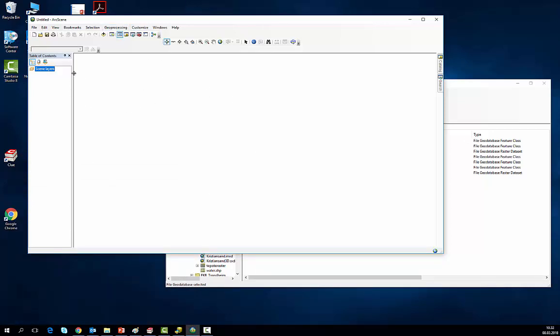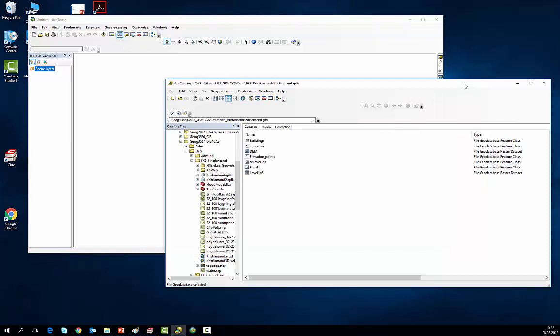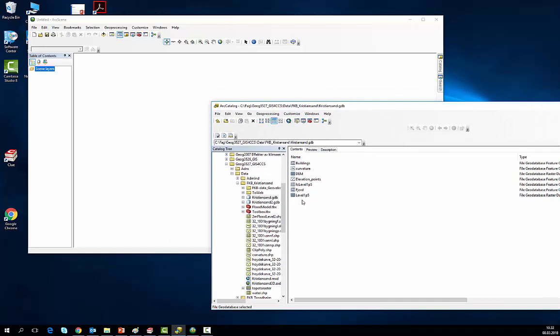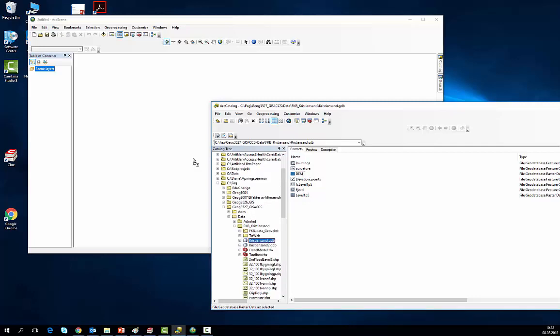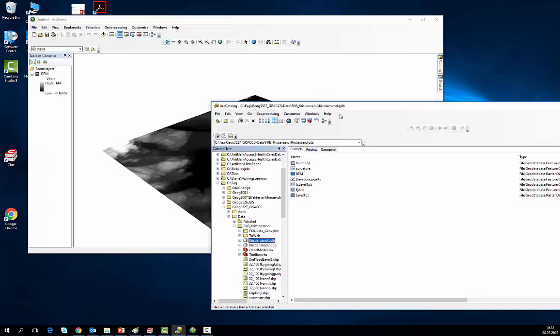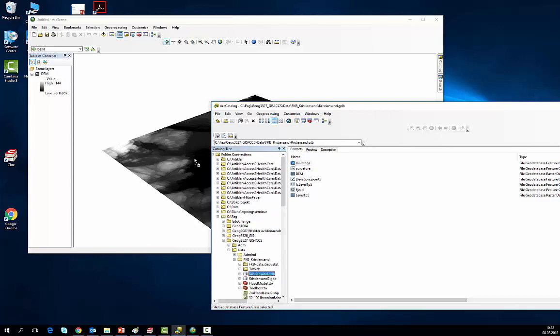document, so you may think it seems a little bit like ArcMap. It has the menu bars and the toolbars, and you can show data very similarly, having a table of content, etc. So what we do now, we're going to enter a digital elevation model. So I just drag and drop it from the Arc catalog, and we have some buildings which we will see the exposure of, and we have from the Python script generated a simulated sea level rise of 1.5 meter, which is also then put into the view.